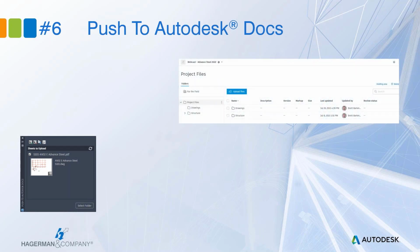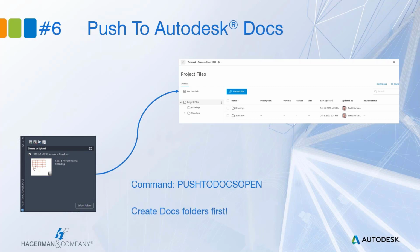This is a great feature, and it's available in all AutoCAD-based products. Even if you don't want to put your entire project in the cloud, you can still send drawings to a project for the rest of the team. You just have to make sure that the folder has been created in Autodesk Docs so that you can select it when you push a drawing. And if you've never seen this palette before, type in push to docs open on the command line.